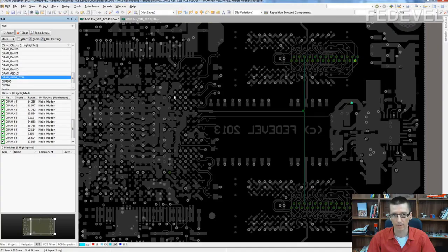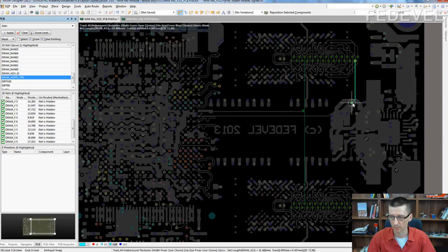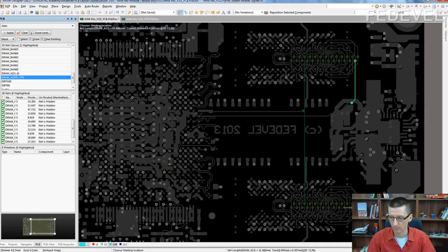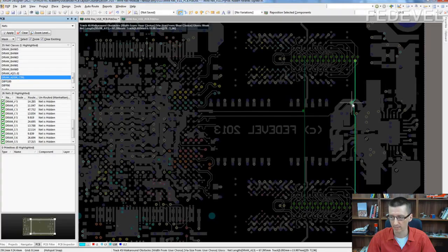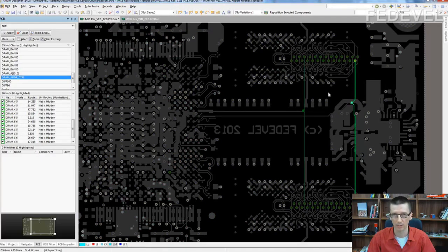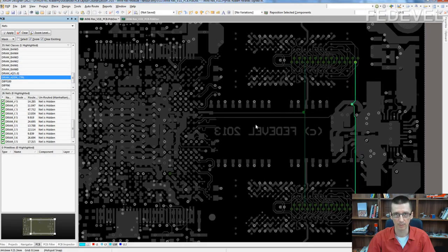Why I don't do the layout this way, that I draw the full connections? What is the advantage of drawing connections from pin to pin? The thing is, it's very easy to route or start doing the layout when the board is empty, when you have a lot of space. Problem is to connect the last 10% or last 5% of your PCB.